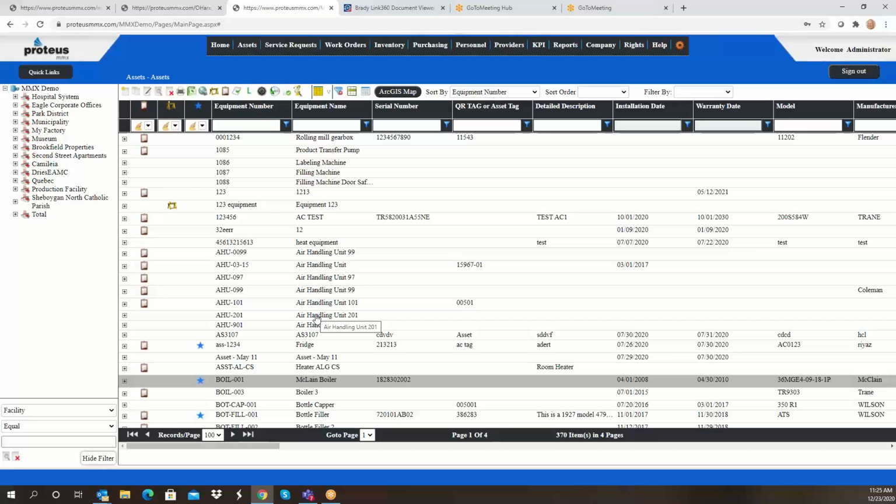So if I'm running an amperage reading, for example, and it should be between 23 and 30 amps, and all of a sudden I'm running 22, 23, 22, 23, and all of a sudden I start trending up toward 30, I can see I have a potential failure pending. I can track and see why my amperage is trending up. So the inspection module and the inspection on the assets will give you that trending data over time.